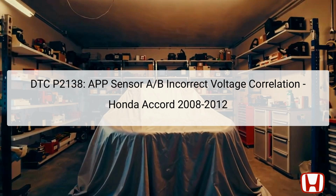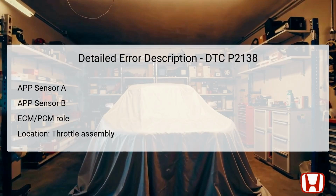Before proceeding with troubleshooting, it's essential to capture any freeze-frame data and a snapshot of the system's behavior to aid in the diagnostic process. The error code P2138 pertains to incorrect voltage correlation between the accelerator pedal position APP sensor A and sensor B. The APP sensors are integral to the vehicle's electronic throttle control system, which translates the physical position of the accelerator pedal into electronic signals for the engine control module ECM or powertrain control module PCM.